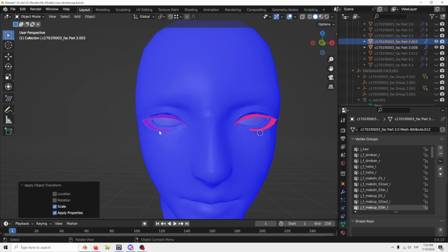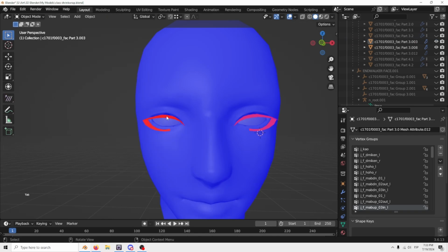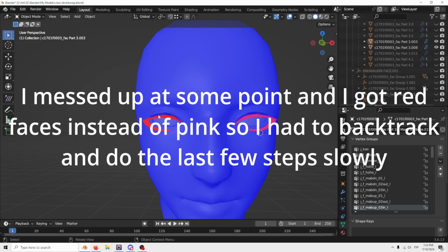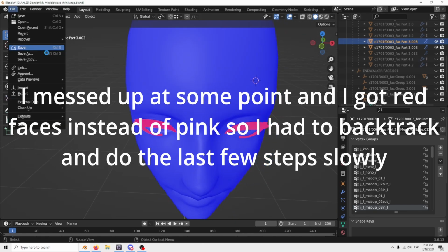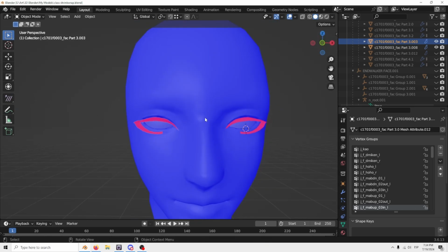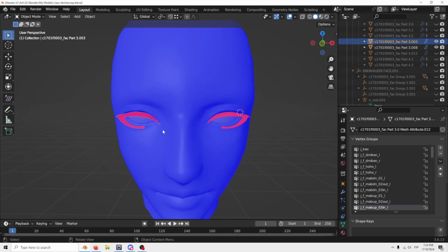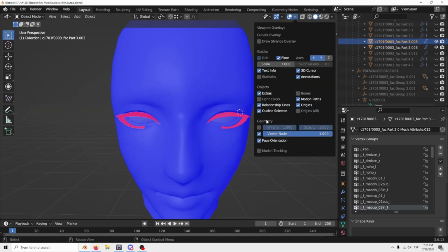And usually what that does is it flips the normals. I think that since I have two sides of the faces now for the eyelashes, this is not going to make a big difference. But just for future reference, once this happens, you go into Mesh, Normals, Flip, and now everything will look as it's supposed to. So now they look the same face-wise, right? These colors mean that I have both in and out faces overlapped, so the eyelashes are going to be visible no matter the angle.